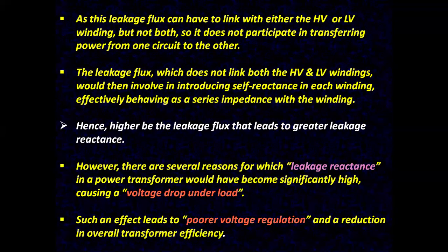This leakage flux can link with either the HV or LV winding, but not both, so it does not participate in transferring power from one circuit to the other.